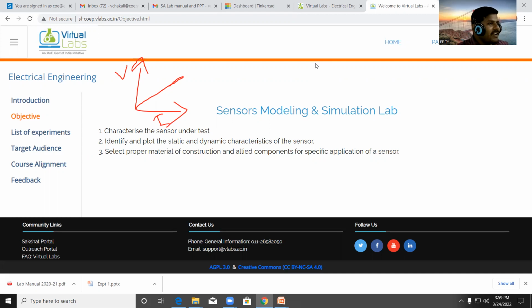So like that we consider one room temperature, or base temperature, which is nothing but R0. At that base temperature, what is the value of resistance, right? And if the temperature of that material increases, then what is the value of resistance? That means RT is R0 into 1 plus alpha 0 T.